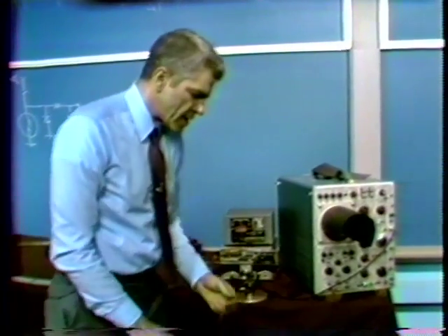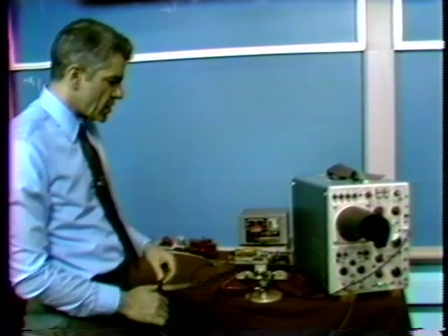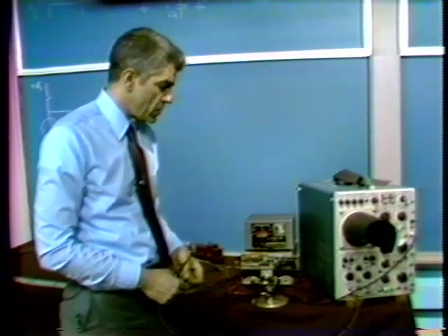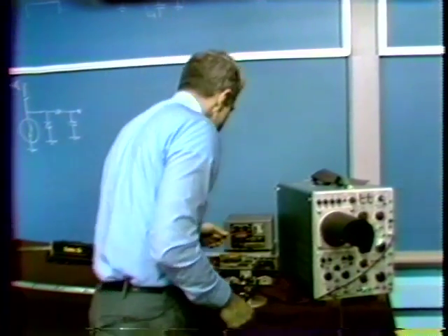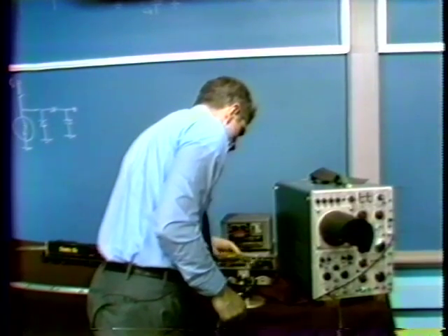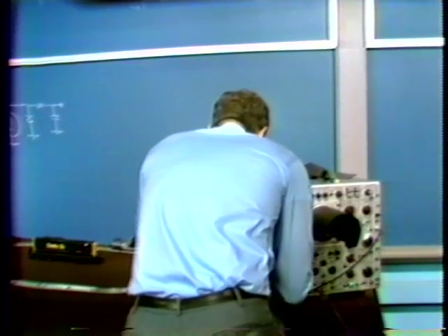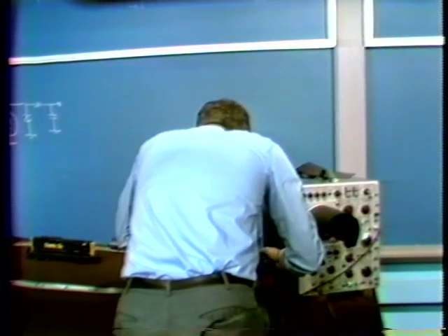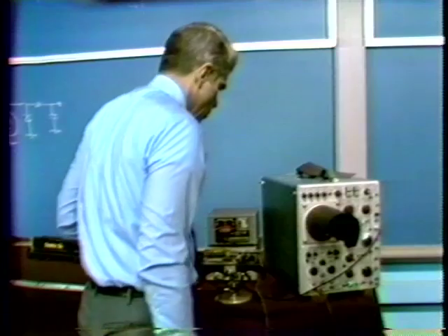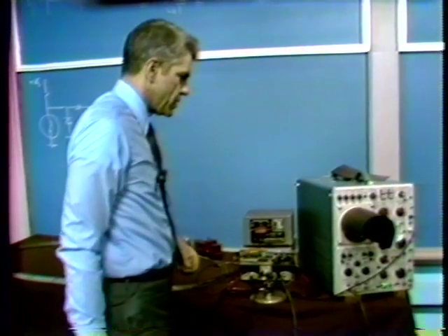The reason I didn't use that as a speed measuring scheme is simply that we get some additional low-pass characteristics out of the averaging network. That's perfectly all right to observe the speed, but if we use that information as part of the loop, we'd have additional stability problems. So I do have provision in here for monitoring the speed of the engine and getting an analog measure which we can display on the oscilloscope.